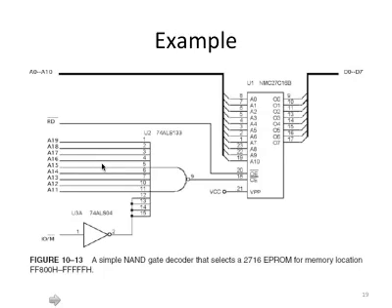Read control: if you have a 0, you're going to do the output enable for this chip. The other control signal is this IO/M bar. This is a control signal to tell the subsystems outside the microprocessor whether this is an I/O operation or a memory operation.